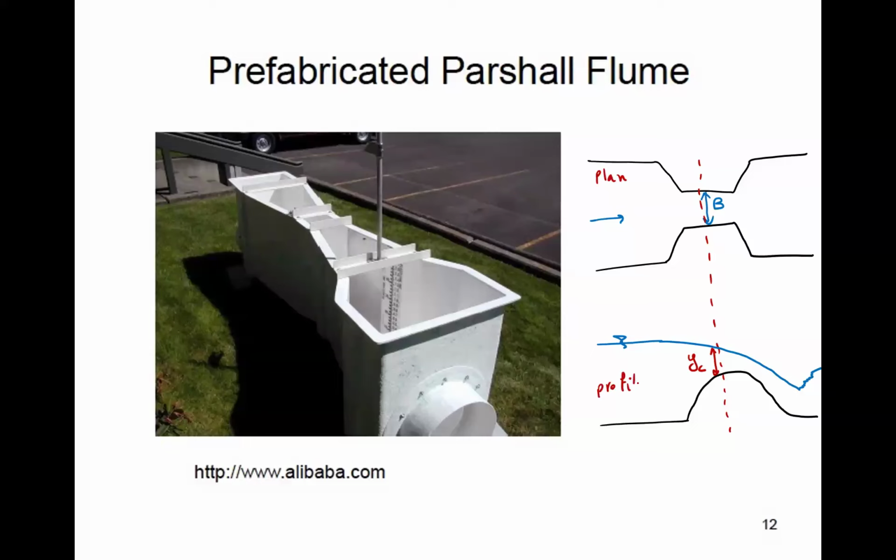So this is again the same idea, a measurement device, usually for relatively small flows. I say relatively small because the one we have in the image is probably a couple of meters long and maybe less than half a meter in width, but there are really huge ones, maybe 4 or 5 meters wide, partial flumes. But again, not very common because maintaining and managing these is not super easy. So not very common for measurement, at least in large canals and streams.